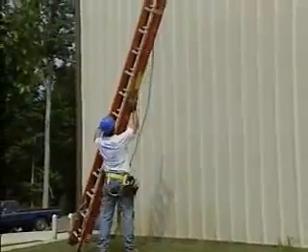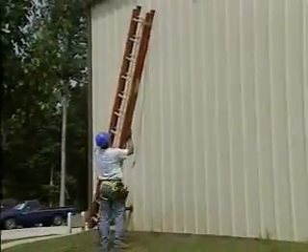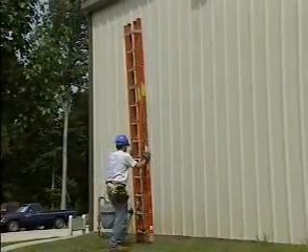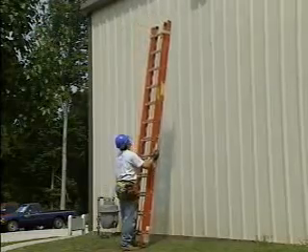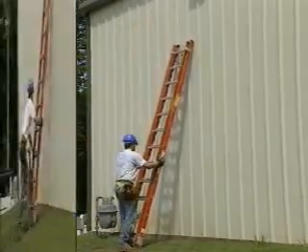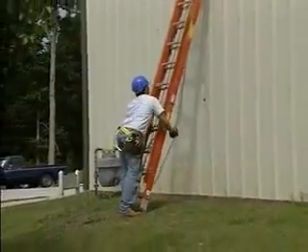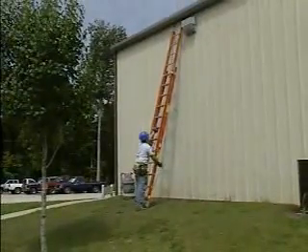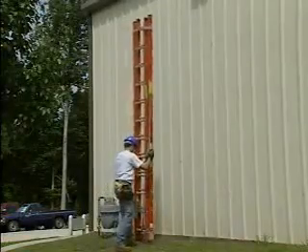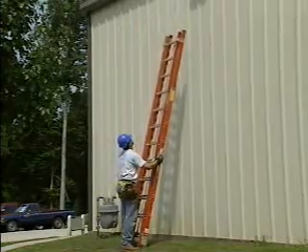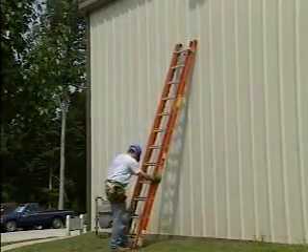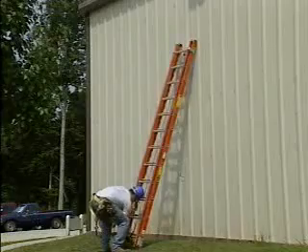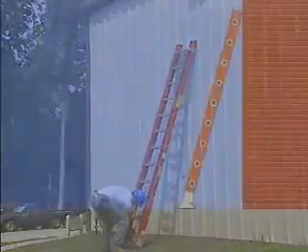As the worker positions the ladder at the job site, he makes sure that the feet are securely set and that the narrow section of the ladder is at the top. He adjusts the length of the ladder from the bottom, where he can clearly see the rung locks. One of the most important rules to remember when you're using a straight ladder or an extension ladder is to maintain the correct ladder angle.